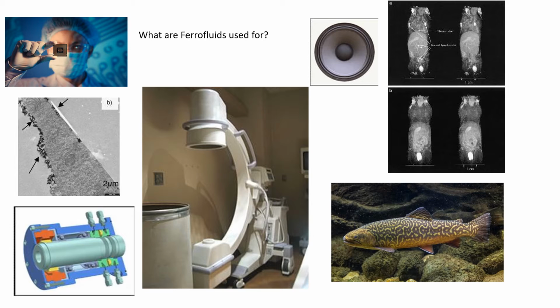Ferrofluids have a wide range of applications. They've been used in rotating shaft seals where they behave as a liquid O-ring, reducing friction relative to that produced in a typical mechanical seal. These rotating shaft seals are found in rotating anode X-ray generators and in vacuum chambers used in semiconductors. Ferrofluids are also used in high-speed computer disk drives to eliminate harmful dust that could cause the data reading heads to crash into the disks.